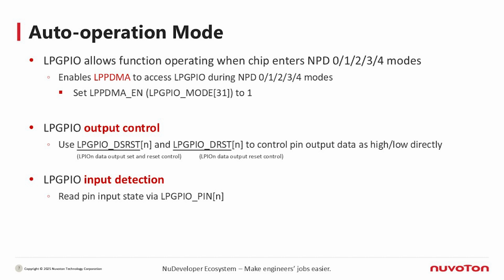Additionally, users can directly control the output pins by using the data output set and reset control register to set the pins high or low. The input status can also be monitored through the pin input state register.